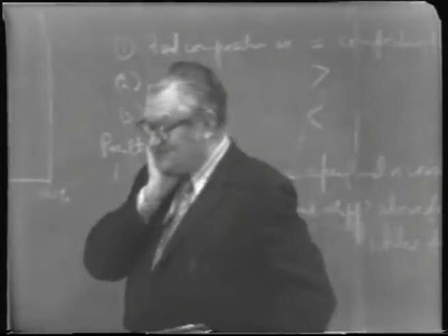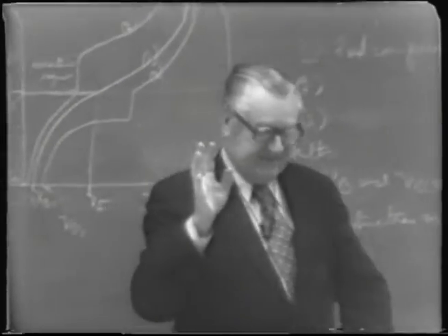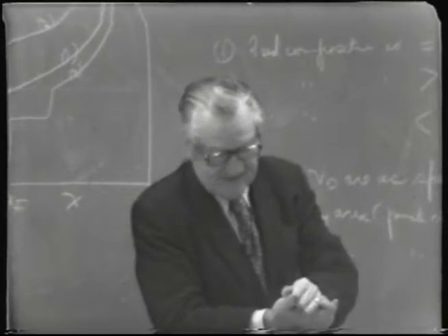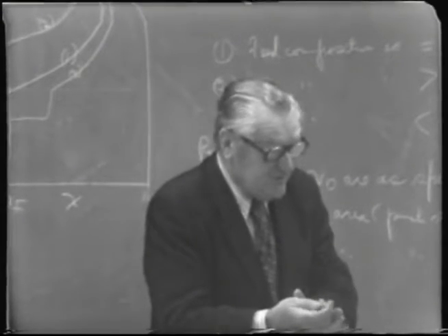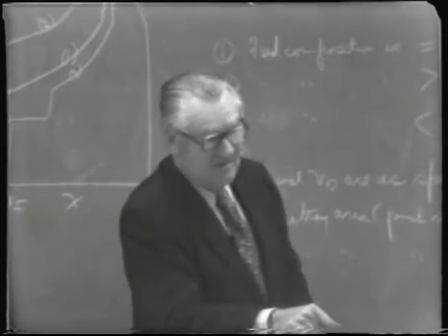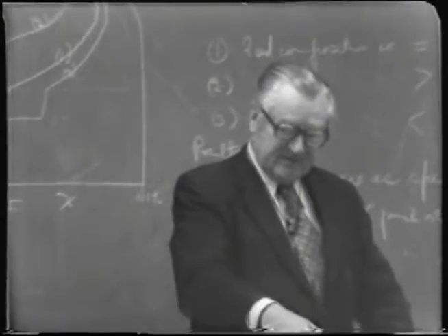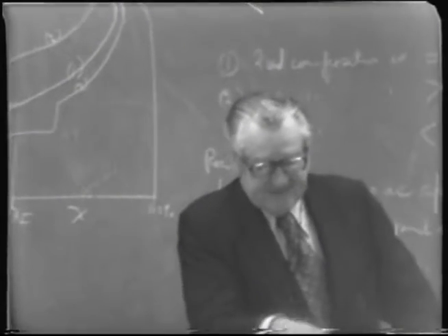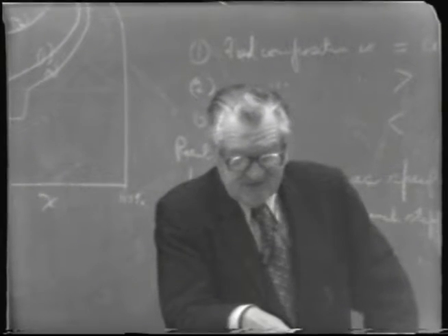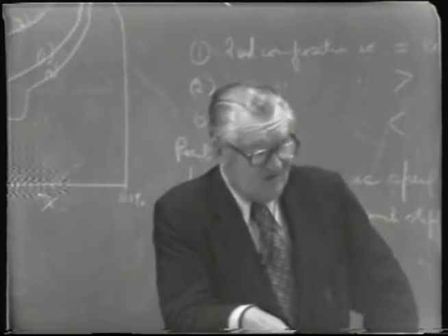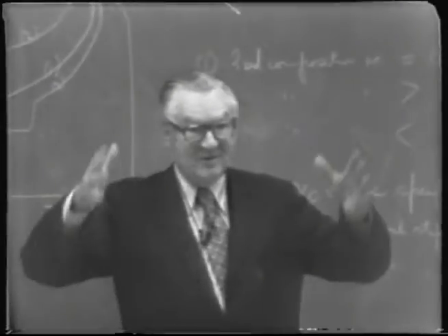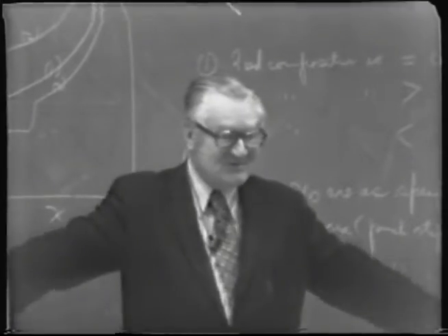What is the disadvantage of using this kind of a system? Well, the only thing is that you've got more metal there and more equipment than originally was required. It may cost more. If you put in a still like that just to produce beverage brandy, you normally wouldn't put in that many trays. But once you have it, you get a better separation of the low volatile constituents into the heads cut, and the cost of operating is very little more than it would be for a smaller or shorter column. It'd be a little bit more because you have more metal exposed, so you get some heat losses to the surroundings and so on.